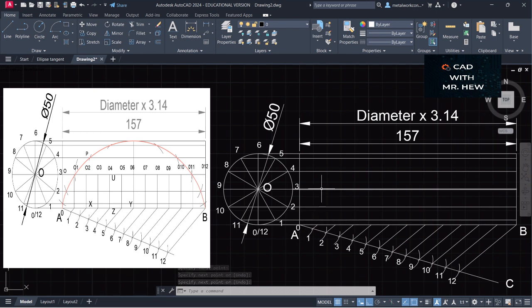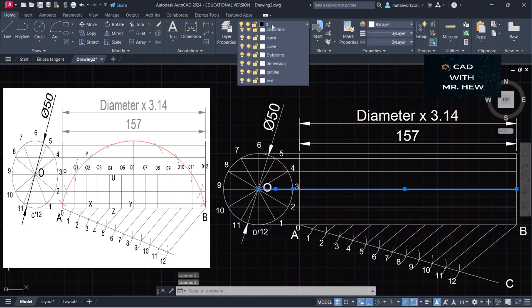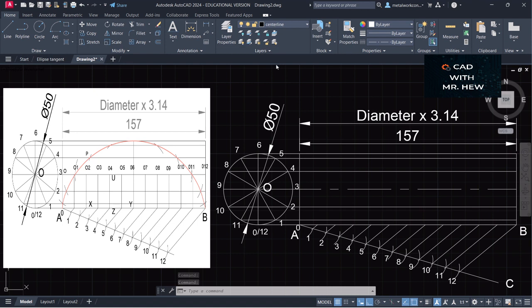Now, this line would actually be a center line, right? So we're going to convert this line and this line to a center line, which would mean how you would darken it using the 3H pencil, all right? Now, it could stay as a construction line because the middle one might not intersect it. All right, so let us undo that.